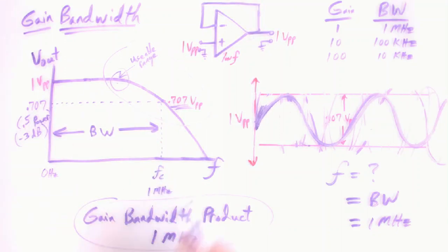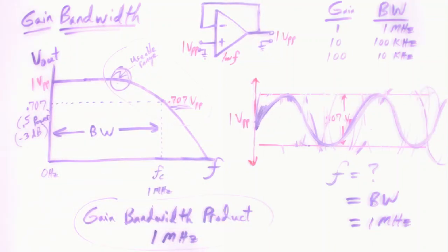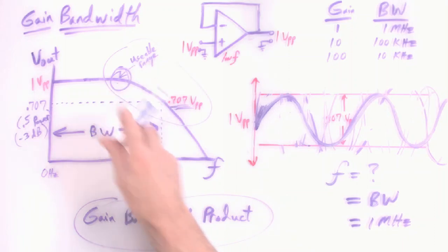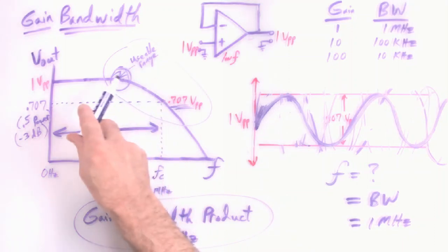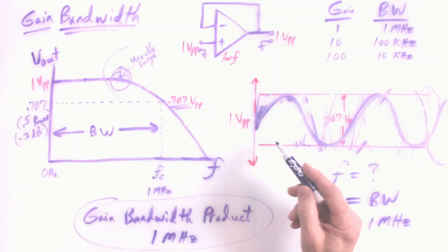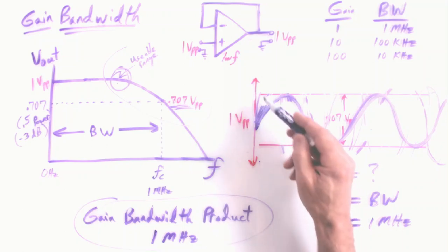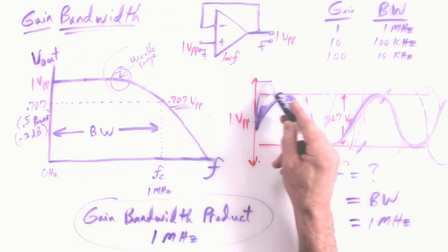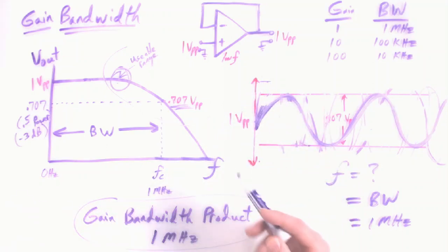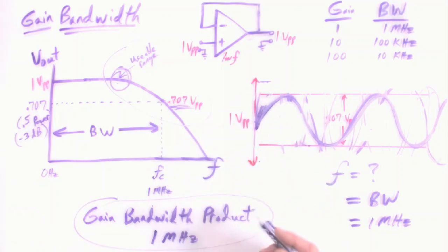I might be looking way back here to say that's my actual usable range. So there's lots of things to keep in mind with all of this. We're not going to get all the way into splitting hairs or backing up to find a usable range necessarily. We could, and if you wanted to do that with your Analog Discovery, you would have your 1 volt peak to peak and just watch for when it starts to drop even a little bit, and you can decide when you want to call it a day as far as usable frequency range.